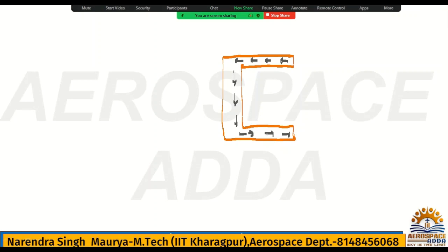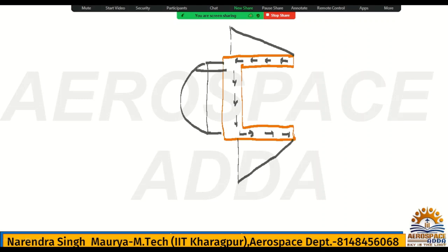If you check the shear stress distribution, I hope you remember, because in BTech coursework you might have solved this problem. So the shear stress distribution will be like this. This is the shear stress distribution for the flange, and if you go to the web, it will be parabolic. So this parabolic distribution will be like this here. Just like for the I section and T section you might have seen, similarly we have a shear stress distribution for the C section.